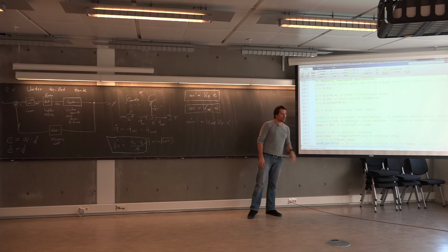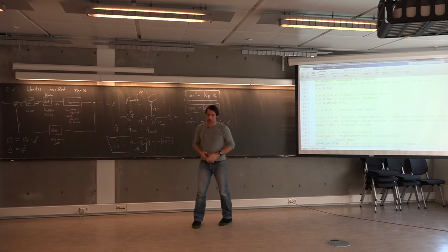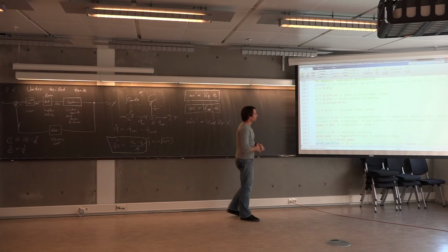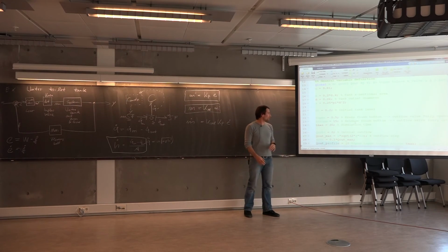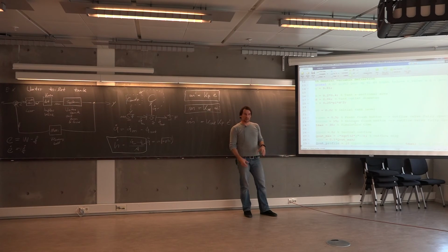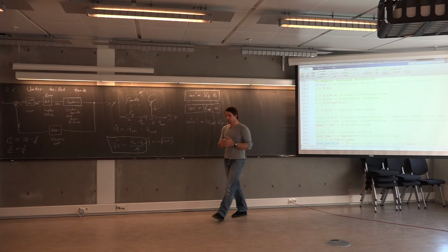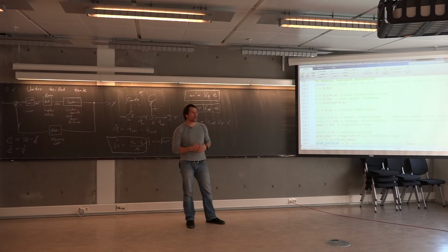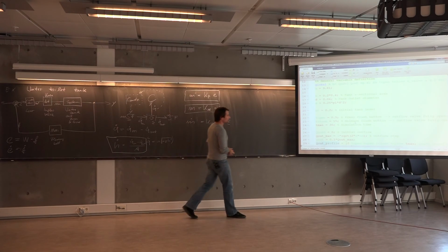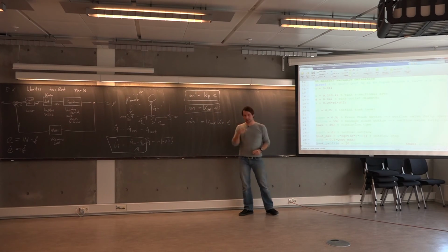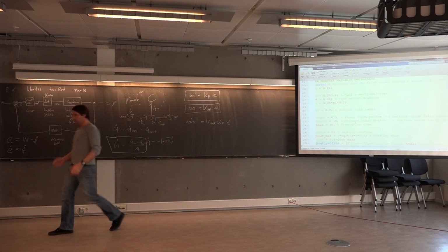At 0.5 seconds, the valve opens. You press the button. And in order to keep it simple and have some meaningful diagrams afterwards, we don't really investigate the case where the water tank is being emptied totally. We just assume a certain step in the outflow. So in this case, it changes from the reference value, or from the initial value, to 90% of the initial value. So there's some step change in outflow. And at 15 seconds, we release the button and set the outflow back to 0.